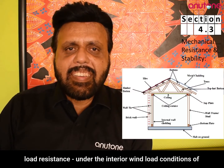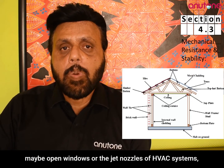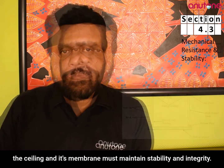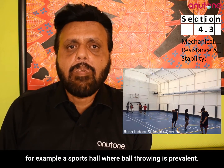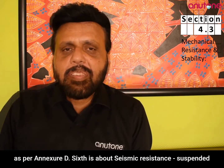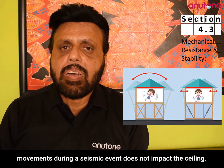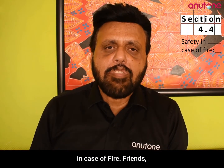Fourth is about wind load resistance. Under interior wind load conditions of maybe open windows or the jet nozzles of an HVAC system, the ceiling and its membrane must maintain stability and integrity. Fifth is about impact resistance. For example, in a sports hall where ball throwing is prevalent, the impact resistance of the ceiling has to be determined as per Annexure D. Sixth is about seismic resistance. A suspended ceiling should be so engineered that vertical and horizontal movements during a seismic event do not impact the ceiling.